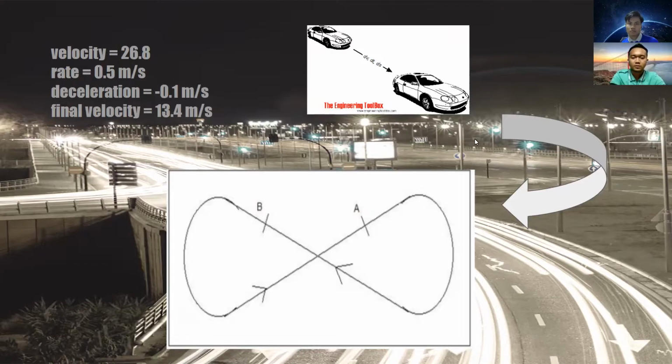The vehicle was subject to hard braking at -1 meter per second squared once it reached 26.8 meters per second, in order to reduce the speed to 13.4 meters per second. The track was designed so that the car takes approximately 3 seconds to complete the curve. This 3-second time slot was also taken into account in the numerical simulation of the phase of acceleration and deceleration.